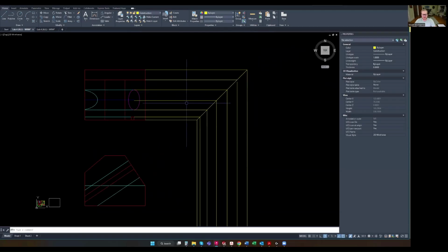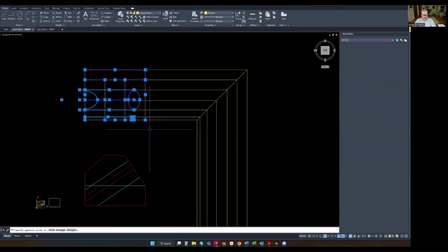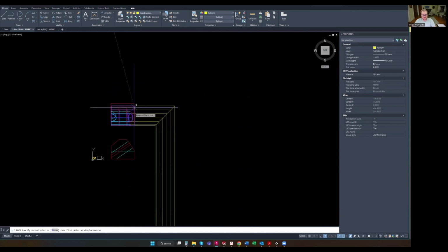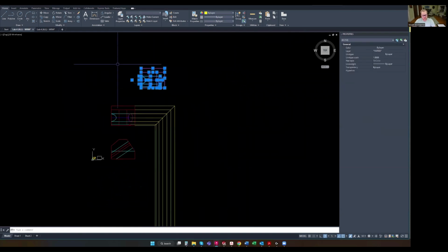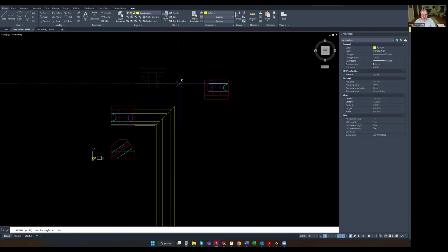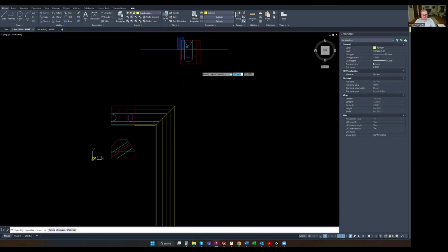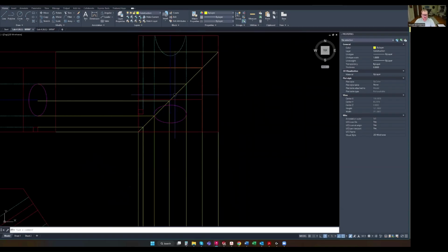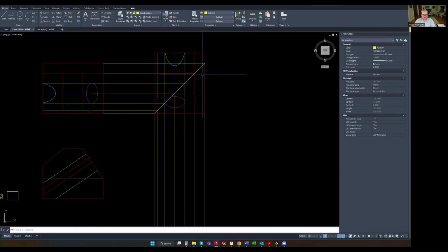And what we're really doing here, if we had a copy of this, what that 45-degree line allows us to do is if we had a copy of this and we just rotated it, we can take this and literally just set it down right here. So all we're doing with this projection line is not having to copy and rotate this to create vertical extension lines directly from this drawing.